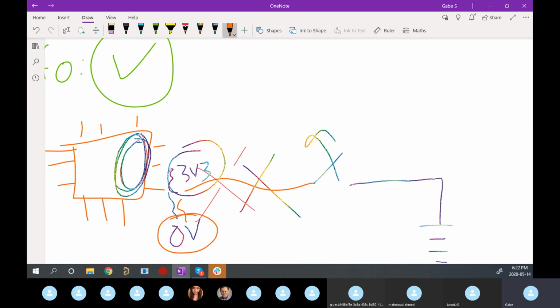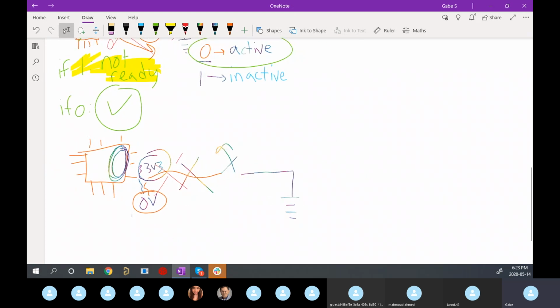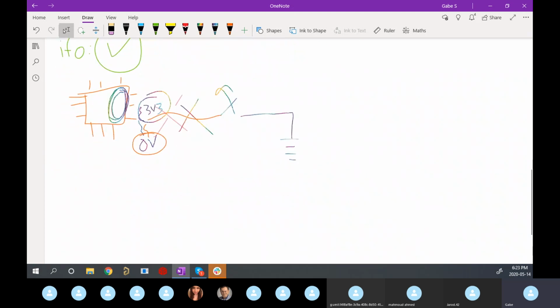If we accidentally float to 0 volts because we're an active low system, our code will interpret that as an A-OK, saying we're active, let's start this car. But for all we know, the car's on fire, everything got disconnected. And obviously you're going to be checking other signals in the system. This is just an example of why a pull-up is really important in a GPIO input.